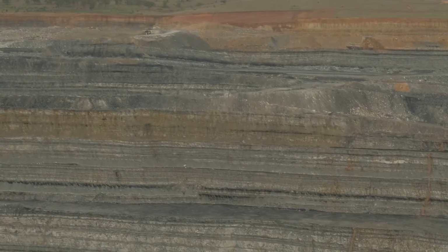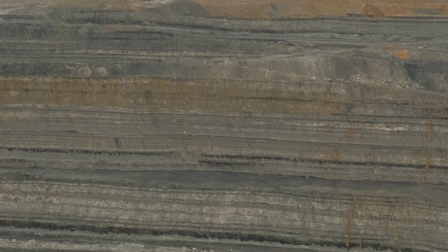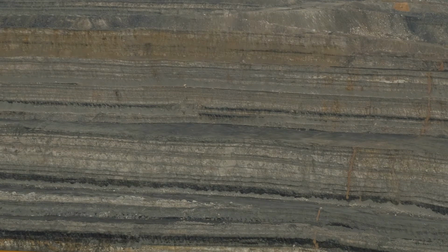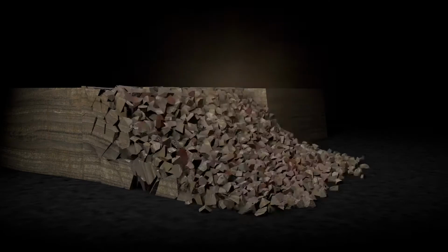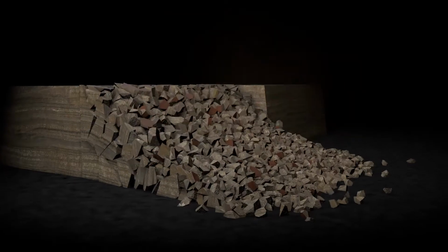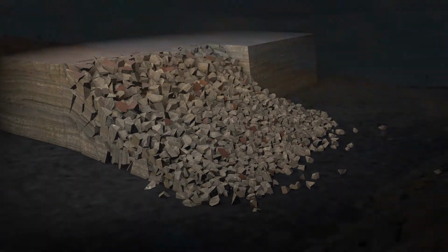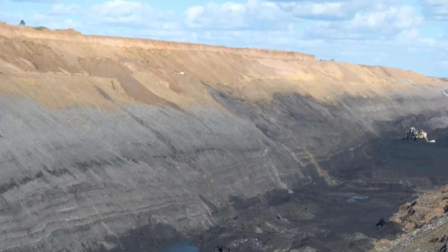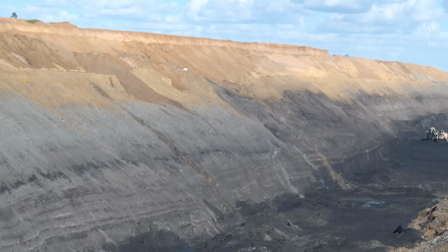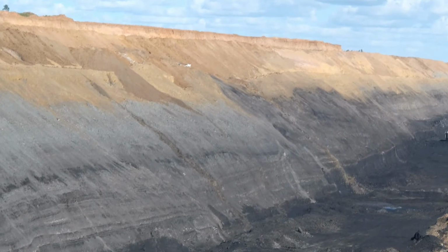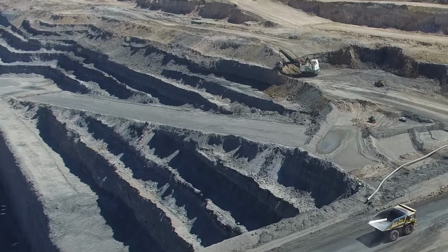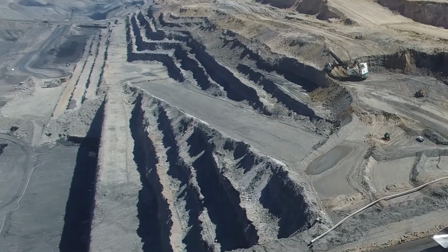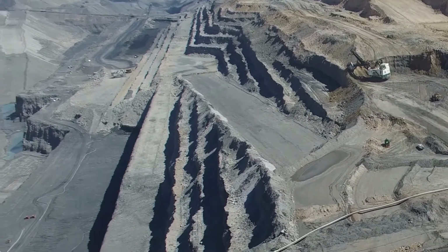High walls and end walls are usually hard walls, that is, their exposed face is excavated through undisturbed rock. They may also be fully or partially blasted to form what is called a soft wall or buffer wall. The purpose of this is to disrupt any persistent structure behind the high wall or end wall face with the intent of increasing slope stability. Benches may also be incorporated into both excavated and dumped slopes to increase slope stability.